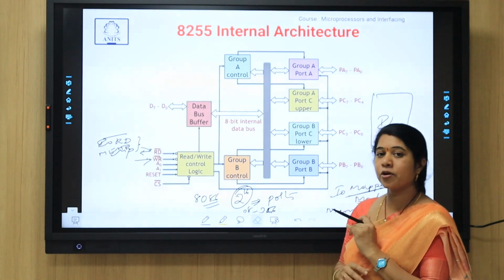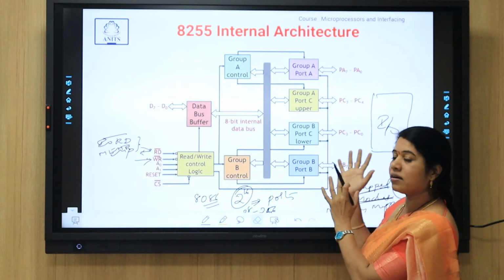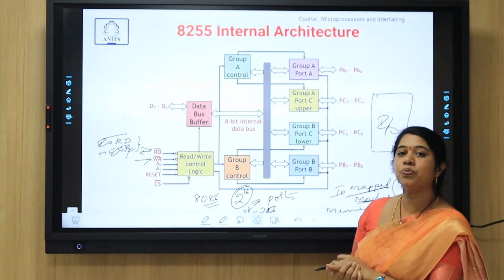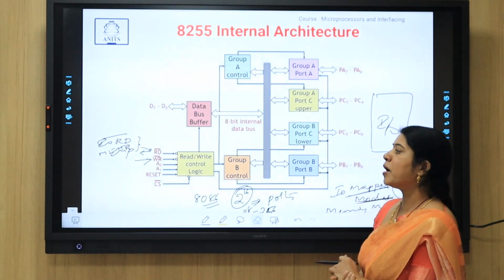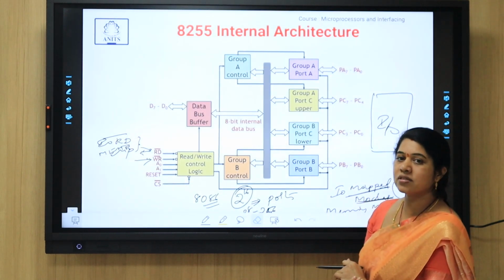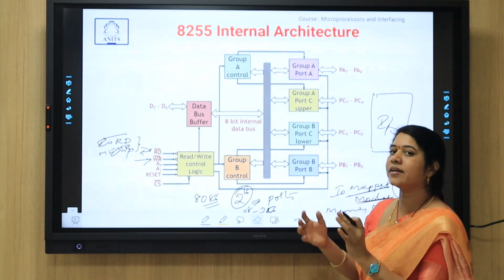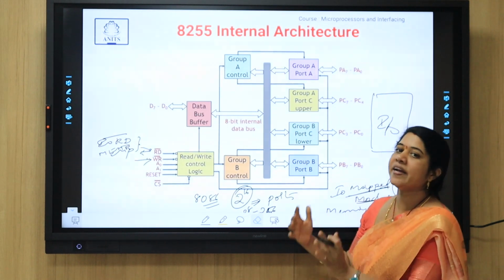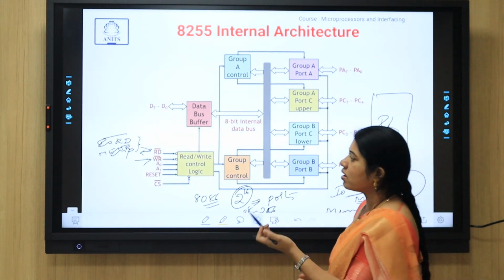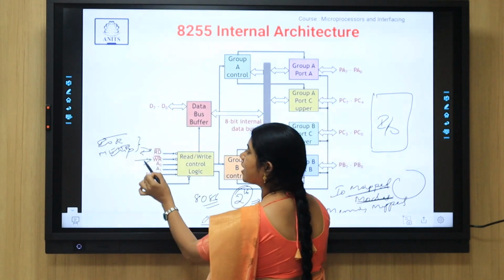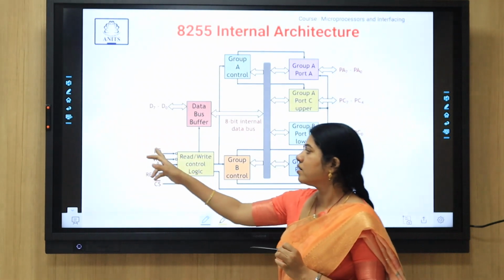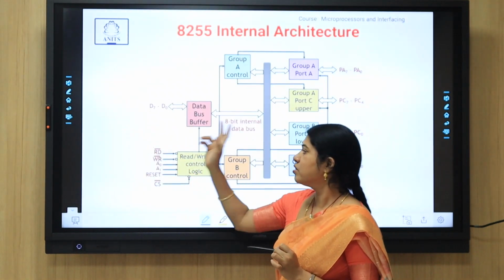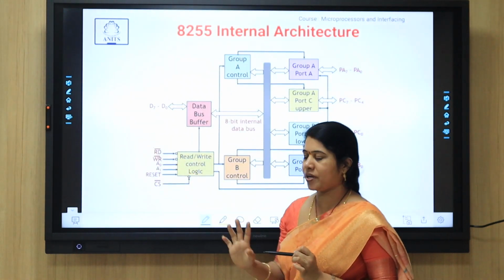And also microprocessor can interface the input output devices through the memory mapped IO mode also. During the memory mapped IO mode, processor uses 20-bit address as like it is identifying the memory, it identifies that IO device. So like that the processor selects either IO read command or memory read command to select the IO device to perform read and write operations.